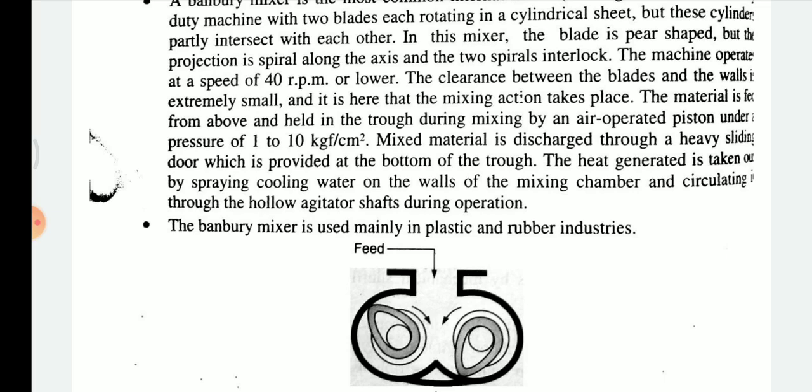The material is fed from above, and during the mixing it is pressed by an air operated piston under pressure. It consumes 1 to 10 kg per centimeter square pressure. Mixed material is discharged through a heavy sliding door, which is provided at the bottom of the trough.